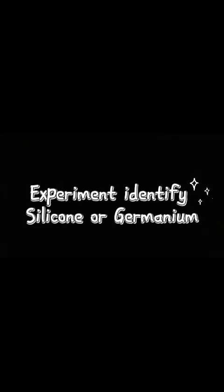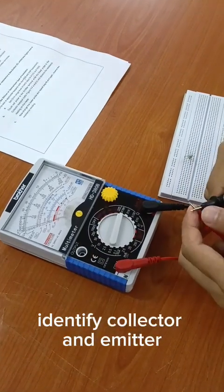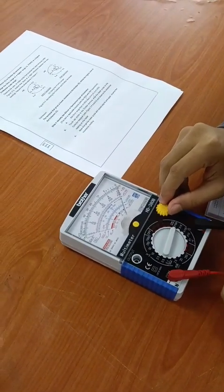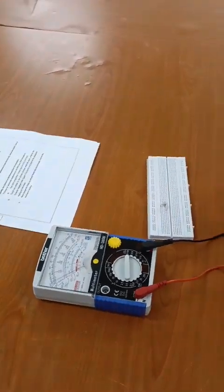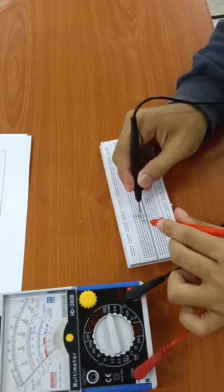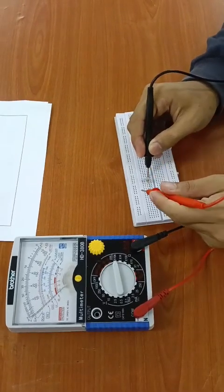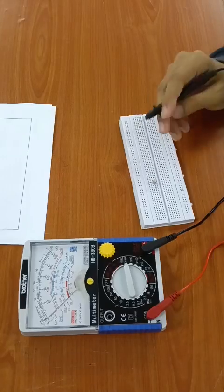Okay, now we go to the experiment on how to identify silicon or germanium. Okay, first we find the collector and emitter. Okay, do zero adjustment at divide by 10k. Okay, put the black probe to base and red probe to another 2 points.